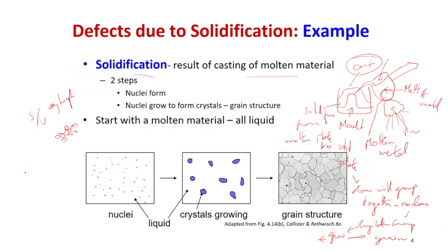As they become bigger and bigger, the surface to volume ratio becomes, what can I say, smaller. Okay, that is when the island becomes bigger and bigger. Island means the nucleus growing. Okay, if that growth becomes larger and larger, what will happen is, in the three-dimensional space, the volume becomes more, whereas the surface area becomes comparatively lesser. So as a result, the process begins to slow down when the grain structure starts to form. So that is the actual process that goes on over there. So I hope I haven't misled anyone by saying that, but it's actually a fast process initially. Then once it forms grains, and the grain grows, that will be a slower process. So I hope I was clear, right?